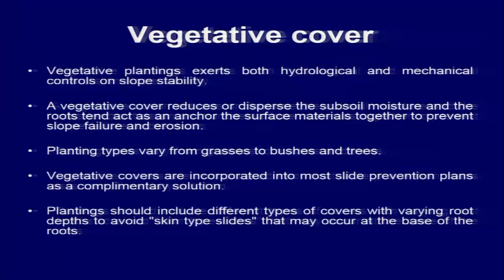But of course, if you are planting very heavy trees which can put additional load on the slope, that can also trigger the landslide. So one needs to be very careful about what type of vegetation we can plant on the slope depending on the material.